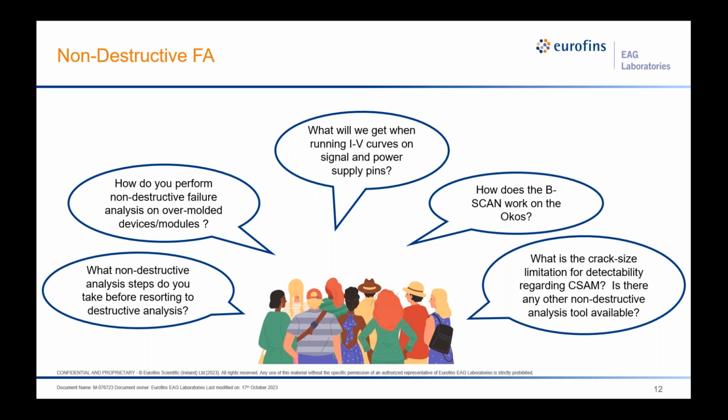So without ATE test results, these IV curves give us a good indication. We test the pins of interest and get a good idea of how the IV curves look, and other times the test spec on the tester might be pretty wide, and on the bench, when you do IV curves, you can set a pretty tight spec and see the minute difference between the failing pins and the pin of interest and a passing pin. So a lot of times we do, say, transceiver pin analysis. We can catch very subtle failing pins that are caused by ESDs. Yep, thank you. Great. And as we mentioned, some of this non-destructive electrical characterization work we actually use to precipitate and kind of design the next level.